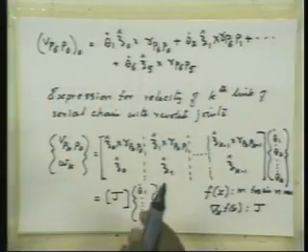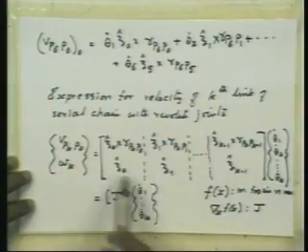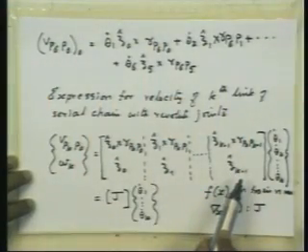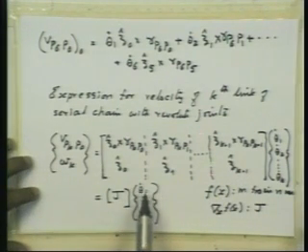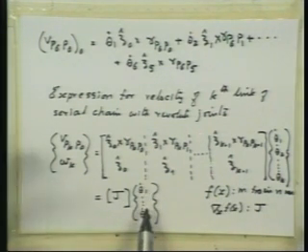Okay. Further, one of the important pieces of information that we get out of this is the following. In various positions of the manipulator, remember these are functions of the position, what is the ability of the joints to impart velocities in all the directions that you want?